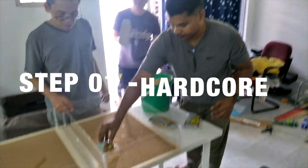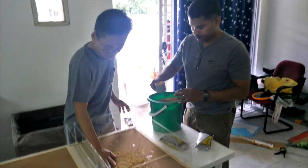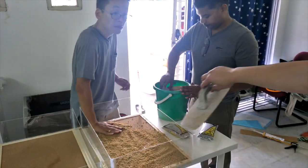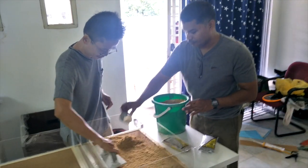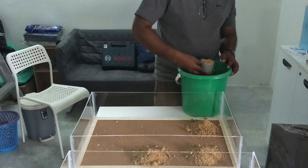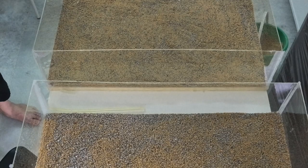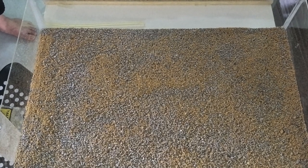Hardcore refers to the mass of solid used to raise level. Its function is to provide a firm working surface, reduce moisture rising from the ground, and to fill hollows. A variety of materials such as crushed rock, gravel, broken bricks, and coarse sand can be used to make the hardcore layer. Typically, the thickness of hardcore is between 100 millimeters to 300 millimeters. On the working model, we are mixing sand and gravel on both models.